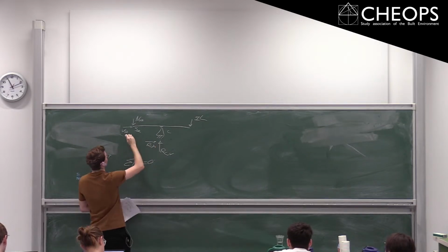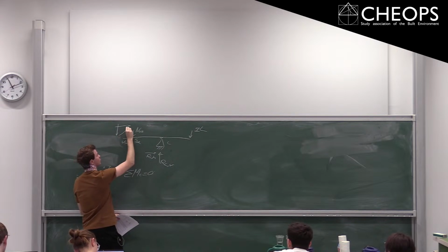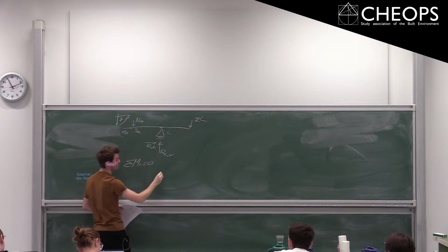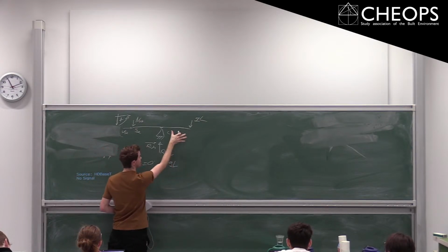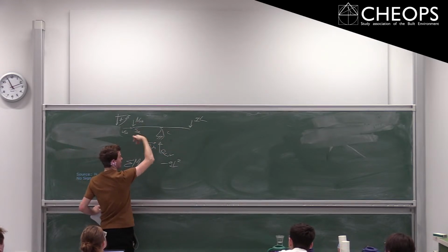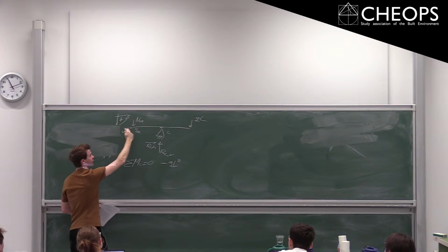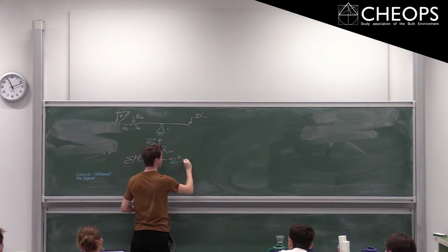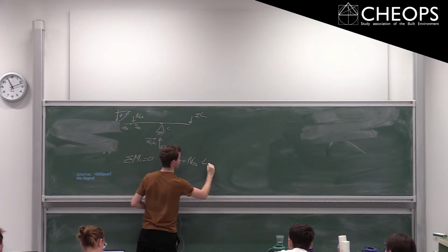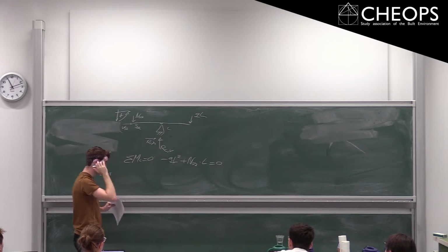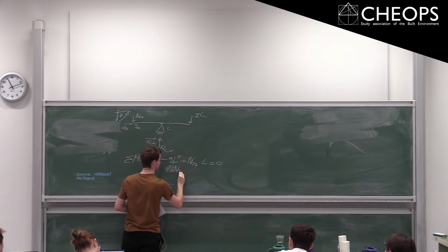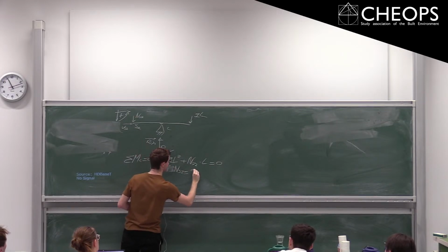So you've got your first, the coordinate system I will be using. Your Q load is going clockwise, so you've got a negative moment, QL, times this is L squared, right? And this one is causing a counterclockwise rotation. This one goes through your point. So you've got only that actual force in S2 times L. And that should be 0, right? And from this we already know that the actual force in your member is simply QL, right?